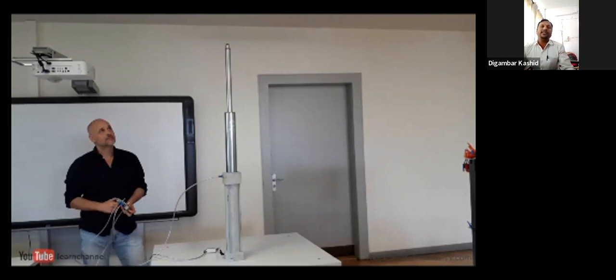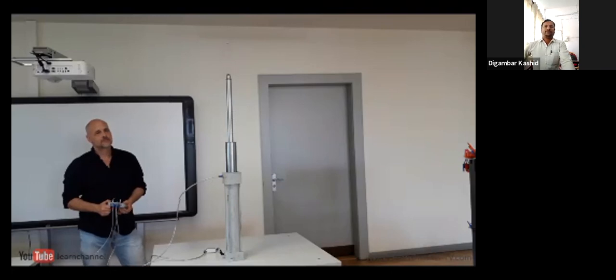Okay, this is called the telescopic cylinder, and this type of cylinder is used in trucks, dumpers and tippers. That is the main application of the telescopic cylinder. Once pressure is switched to the cylinder, the main sleeve first extends. Once this sleeve is fully extended, the next smaller one begins to extend.